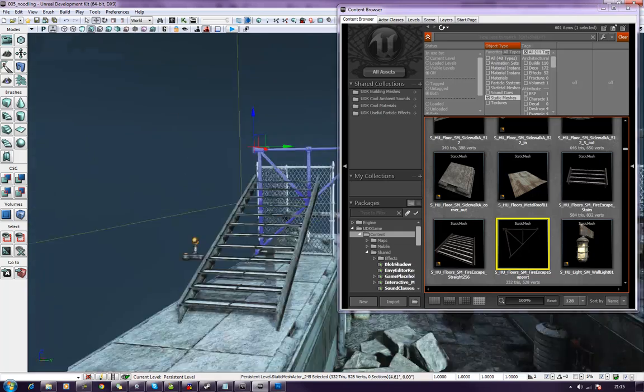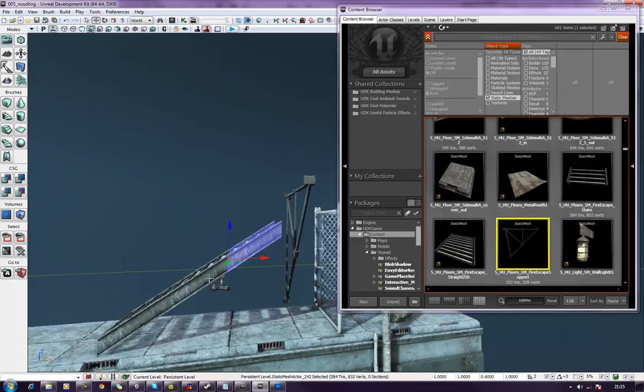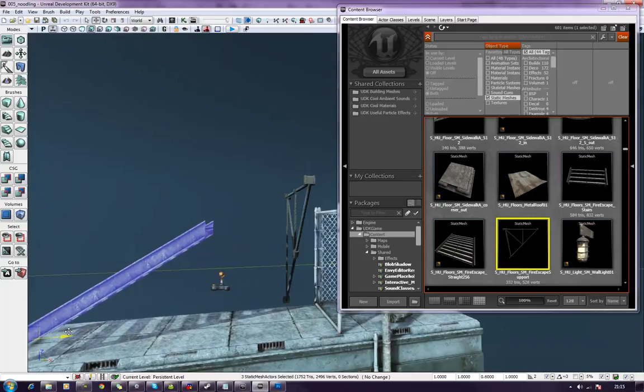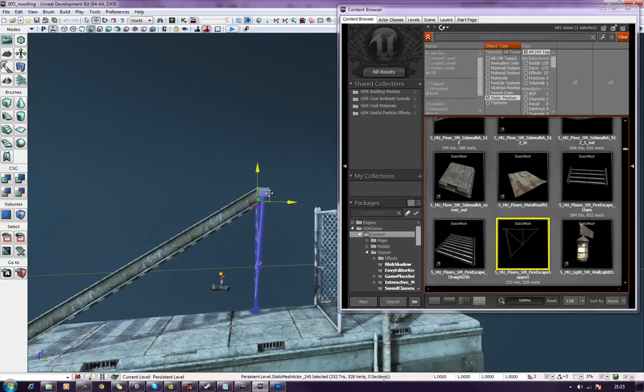Now this staircase at the moment isn't quite what I need, but it will be, so I'm going to bring this back, and then if I hold down Alt, okay, as you can see it's now marrying up to this piece a bit, and you can see that this here will need to be a bit lower down. So let's see how high up it's going to be when I add one more riser to it. It's going to be very high up.